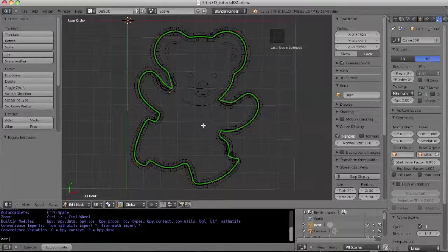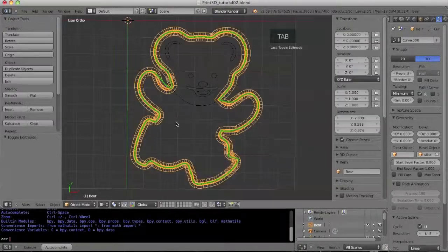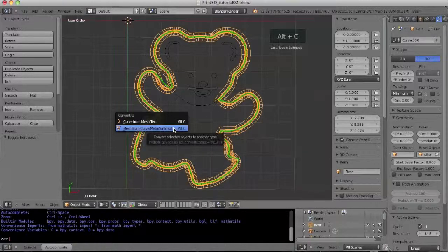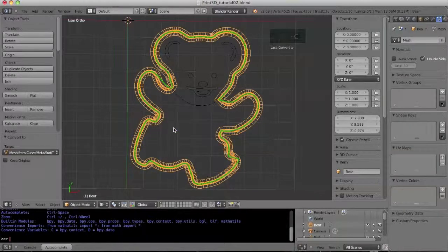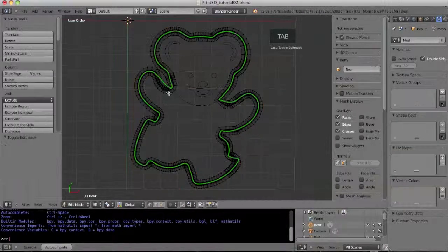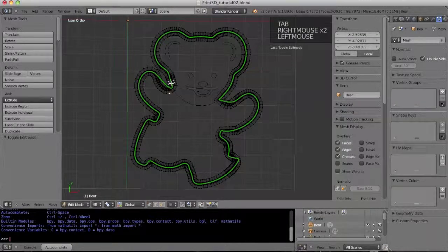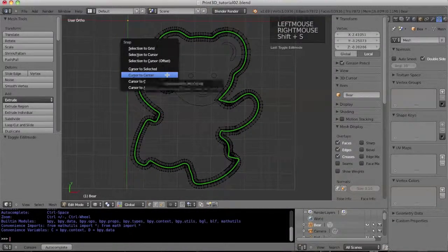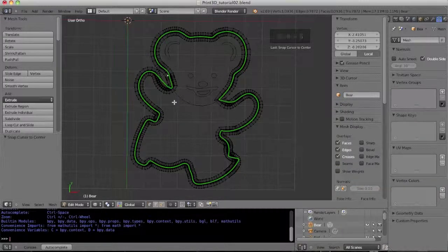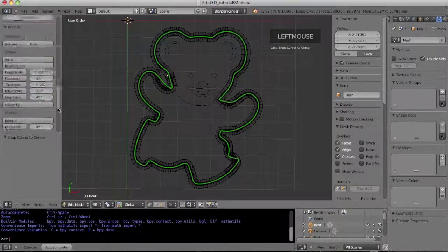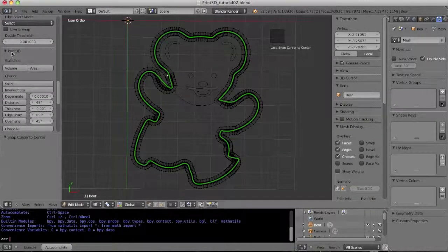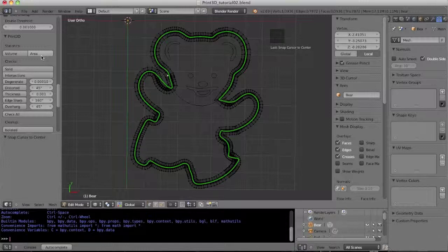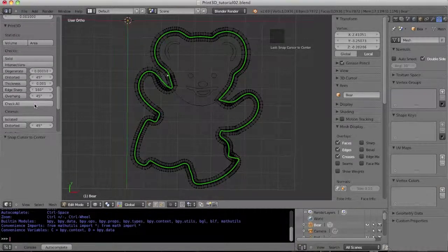To check that, there is the 3D printing toolbox plugin which I have installed, but before I can use it I have to convert the curve into a real mesh. So let's do that and create mesh. Now if I go to edit mode, you see here instead of curve points, we have a mesh available, and now there should be that plugin visible. Here you see Print 3D, and we can do all kinds of checks. The best thing is just to do a check all.